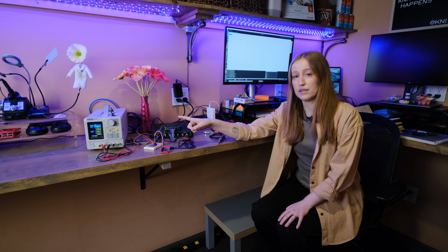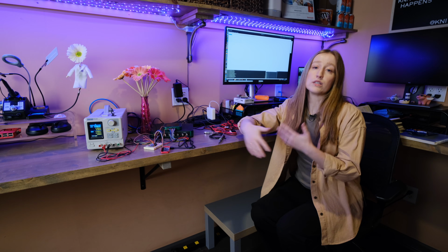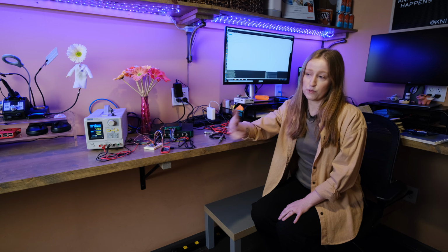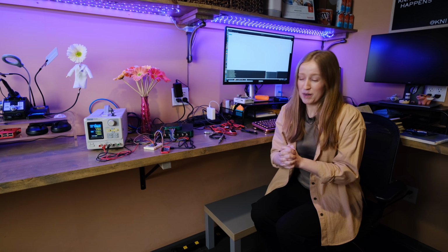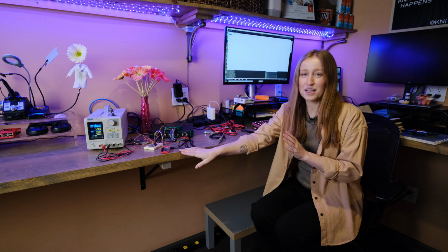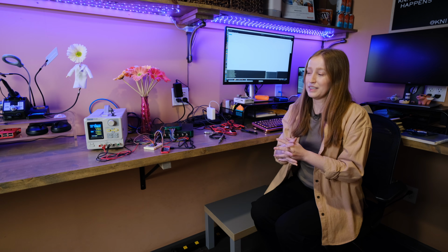In turn, when I give the power down command to the Raspberry Pi over SSH, obviously it disconnects and I no longer have a connection to it. I can then monitor the current to see when it's fully shut down and it's safe to remove power, because I don't want to corrupt my image on the Raspberry Pi, which in this current setup I don't have a way to change remotely. But we'll get into how to solve that later.